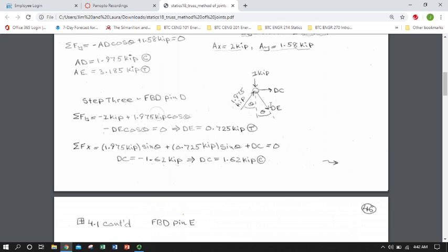Chances are one of them isn't, and that will be shown simply by having the magnitude of the force for that member come out of the equations of equilibrium with a negative. And so that means negative relative to the direction it's drawn, and once I determine its orientation relative to itself, I'll just drop in a T or C.